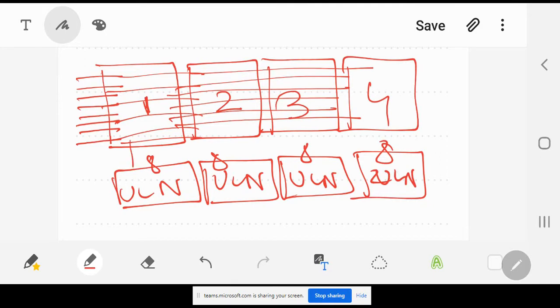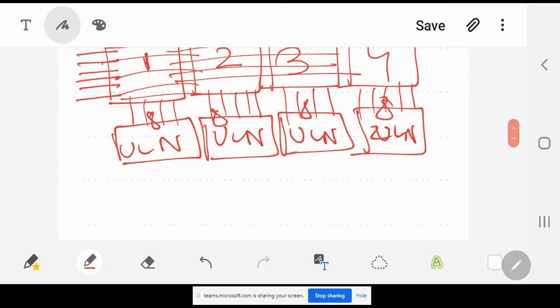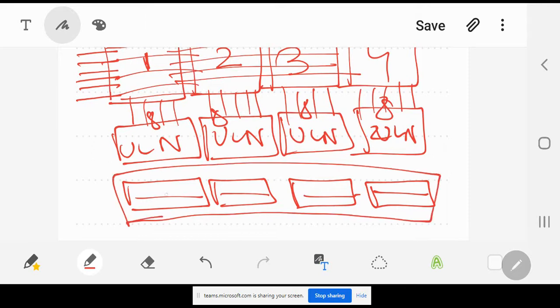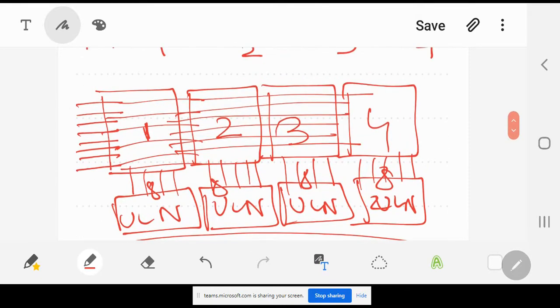So column wise there will be 8 connections here, 8 here, 8 here, 8 here. If you are not using the 74HC595, there will be male headers here, 8 pins here, 8 pins here, 8 pins here, 8 pins here. So this means 8 by 4, that is 32 pins of headers, and when you are using the transistors at this point, there will be 8 pins here also.